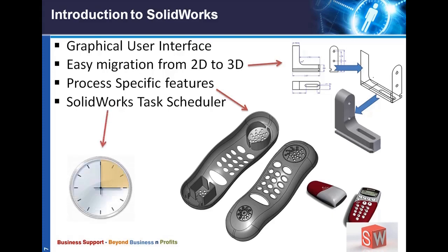The next one is SolidWorks Task Scheduler. The biggest advantage with the SolidWorks Task Scheduler is, say there is a situation. You have a task of updating all the part files which were done in SolidWorks 2008, and you want to convert these 2008 files into 2010 files. In the typical situation, you will open the files one by one and convert or save them. But using SolidWorks Task Scheduler, you can do it as simply as possible.